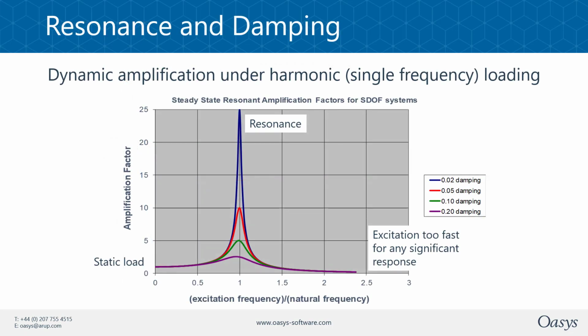So with no damping, the resonance vibrations will be huge. Where the natural frequencies of the structure coincide with the forcing frequencies, then again you get a large amplification of the structural movements. And how much this actually happens depends on the structural damping. Now, the damping factor of a real structure tends to vary between about 0.3% to about 4.5%, depending on the construction and fit out and so on.